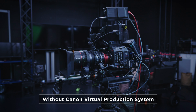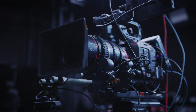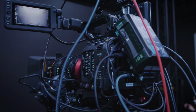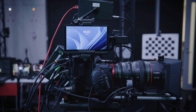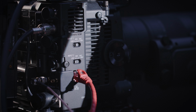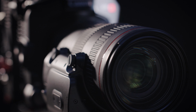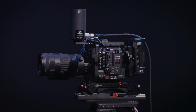Traditionally, virtual production often relied on attaching external lens encoders to capture zoom and focus data. That adds gear, cabling, power requirements, mounting considerations, and more points of failure and variability. With CVPS, lens information is output directly from the camera as CV metadata, eliminating the need for external lens encoders. Fewer components mean simpler, faster setups, cleaner rigs, and less operational overhead.